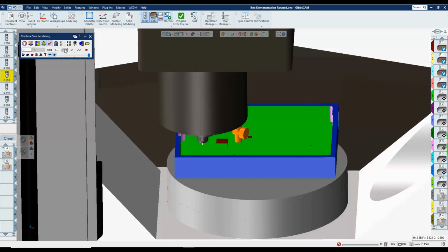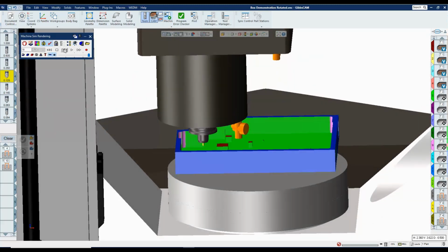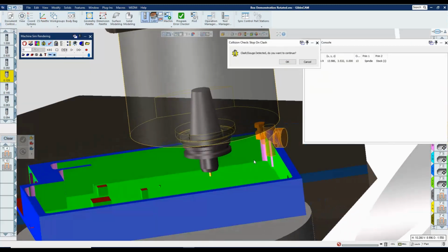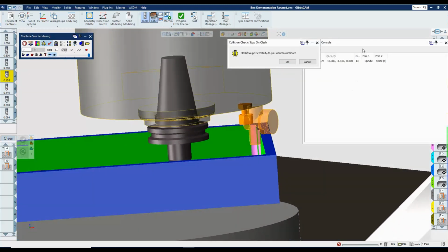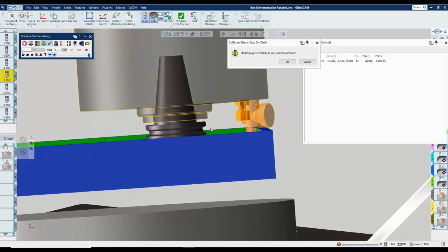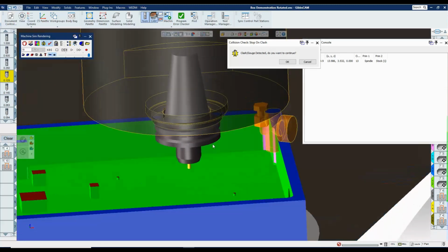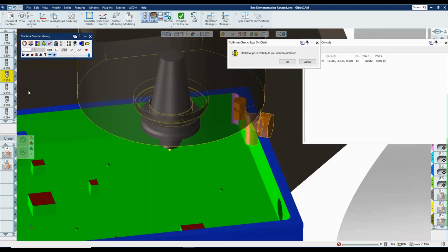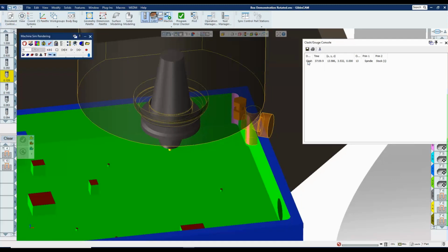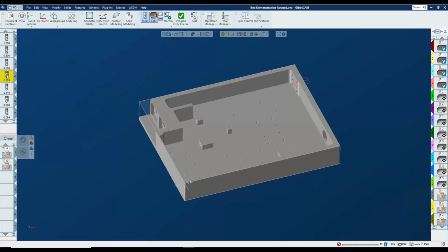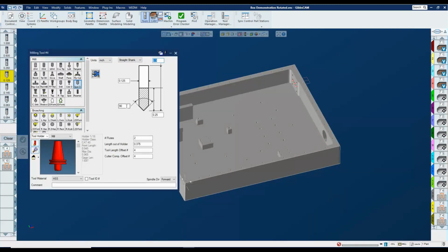And you can see that stubby little tool sticking out. Okay, so far so good, but look at that right there. You notice it's telling us a part of the spindle, which is this nozzle configuration, is actually hitting the stock here. So this stubbiness is going to have to go away. In fact, we're probably going to have to modify several tools to get around this issue, right? So that's what this is for. This is for finding errors such as that.